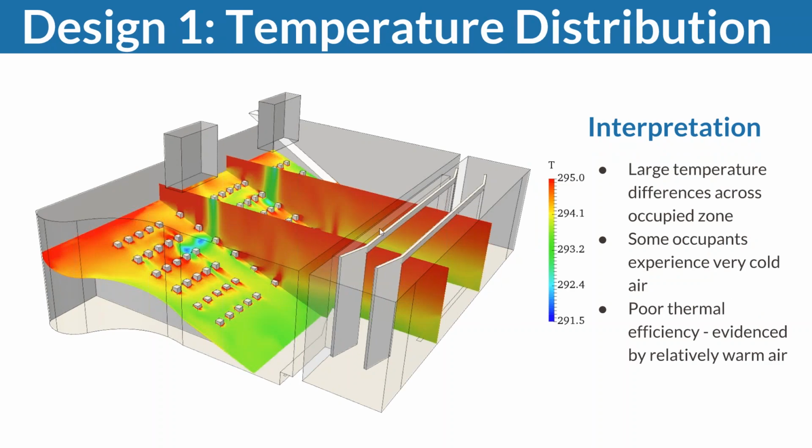Obviously, the temperature here is plotted in Kelvin. So the red piece is 22 degrees Celsius. And also here, right, we're bringing in conditioned air, so cooler air, and it's being heated by the audience. You can see that the audience emits heat. And while around the inlets we've got decent cooling happening at the top, we've got a higher temperature in the occupied region and at the bottom a very low temperature. So again, it confirms our concern that this might not be the smartest ventilation strategy.